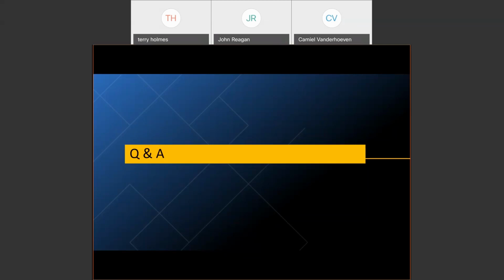Let's go to Robert's question regarding the trampoline routines. Does linker output include information about trampolines to assist in troubleshooting should a problem arise? Bob, you're reading my mind. Today you can infer where the trampolines are, but in my humble opinion, it isn't as clear as it should be. In the linker cross references that give all the addresses, it's on my list to augment that with additional information.